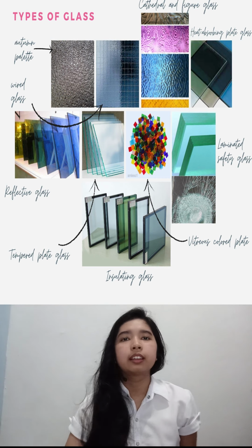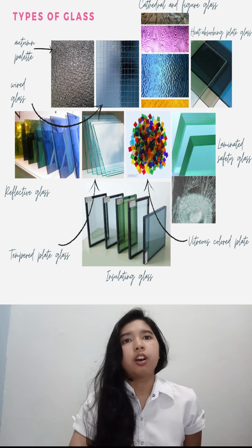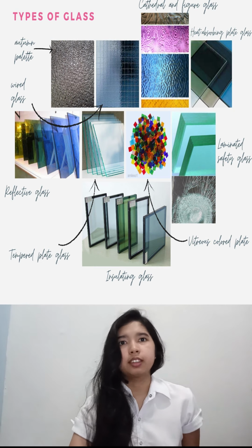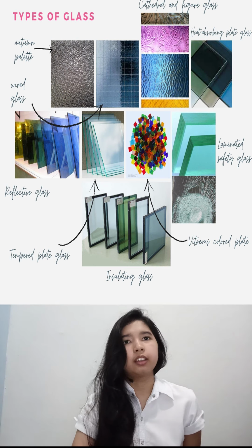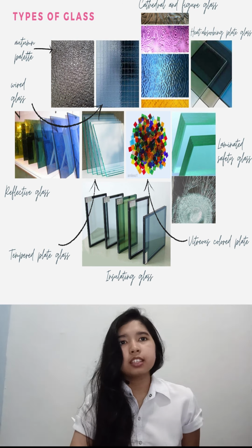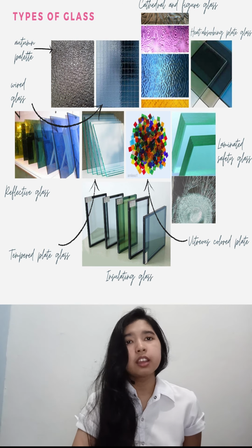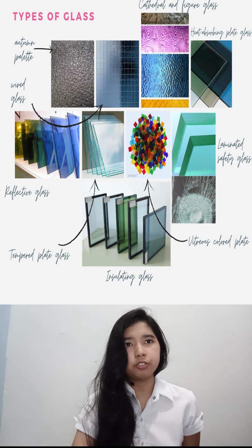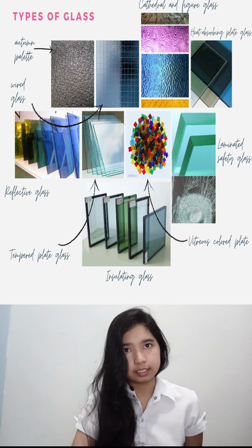Laminated safety glass. It is widely used in the automotive industry and transportation, but now is finding some uses in the building industry, like glass that can withstand firearm attacks and explosions. This is made of 2 thicknesses of plate or sheet glass bonded by a thin, tough layer of polyvinyl butyral resin, a transparent plastic. And lastly, we have insulating glass.